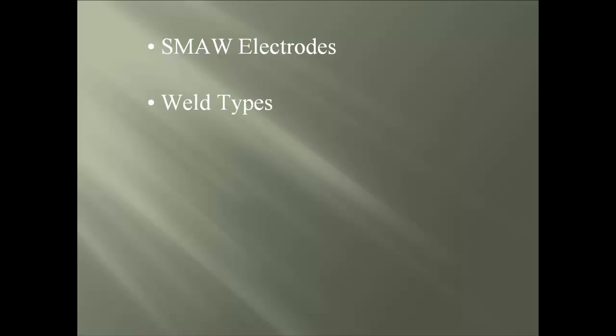The following weld types are approved: the square groove in a butt joint, fillet welds in a lap or T-joint, flare groove, arc spot, arc seam, and arc plug. The way to match the correct filler metal with the base metal being used is found in Table 1.2.